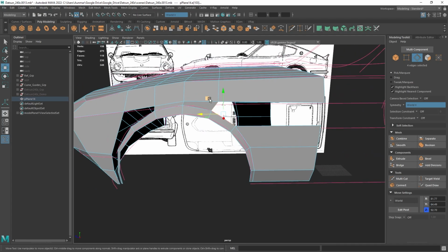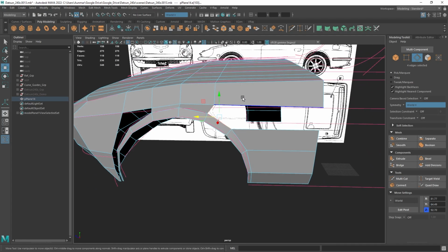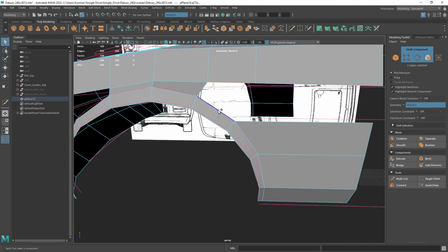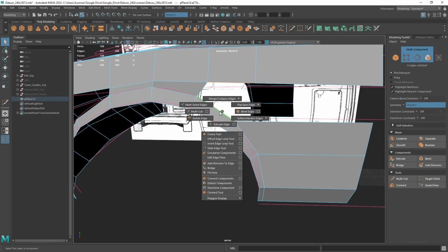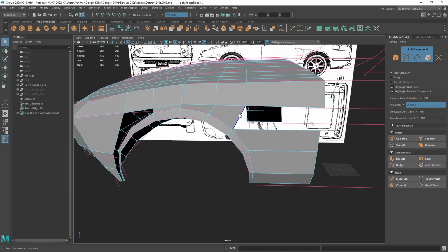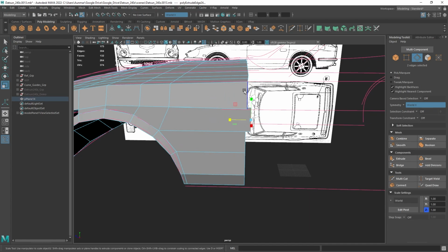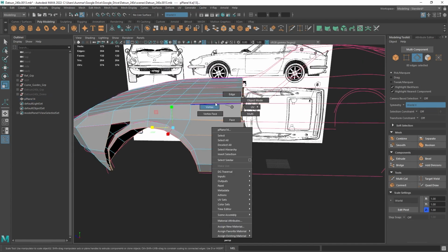And there's a couple different ways, we can add another edge here. So I'm not going to worry too much about it. I'll go ahead and just simply add in another edge here for the hood. And we'll do another bridge. I may have done it a little bit differently in the tutorial or the time lapse, but this should be fine. And then edge copy this. And there we go. And so now we have all of these vertices.